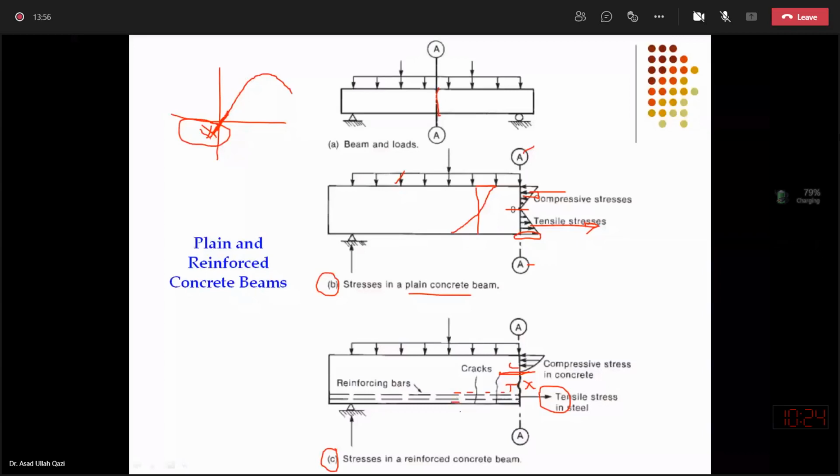It is still protecting the steel from rust. It can still provide us resistance against direct attack of fire. It is still providing us the bond, the resistance against slip of the steel. So composite action is still present. Now, since the magnitude of stress increased, we have moved up in the stress strain relation of the concrete, and some non-linearity in stress strain is getting visible. You are seeing that it is now bending. There is some non-linearity here.